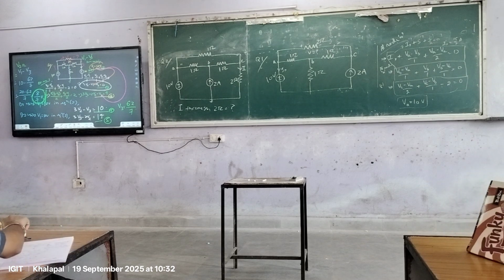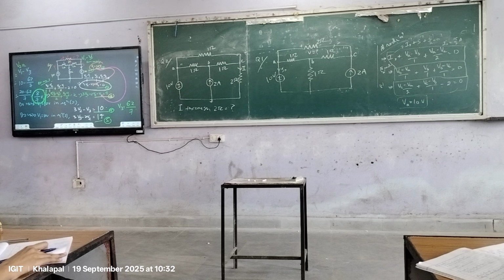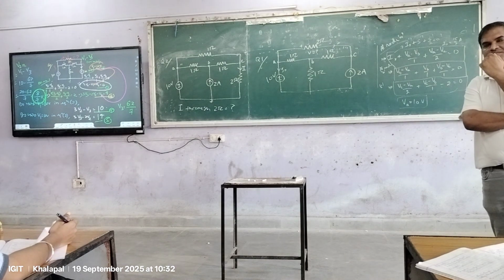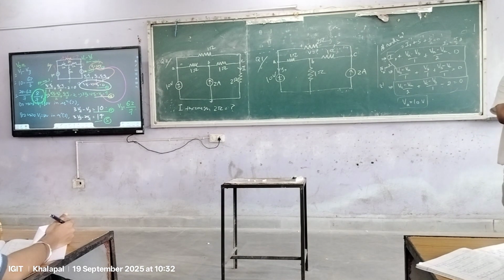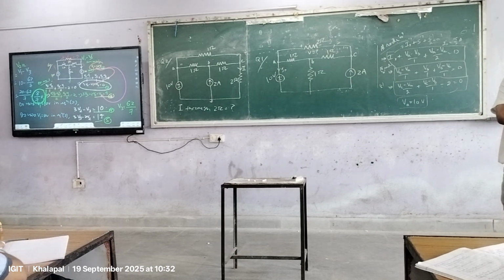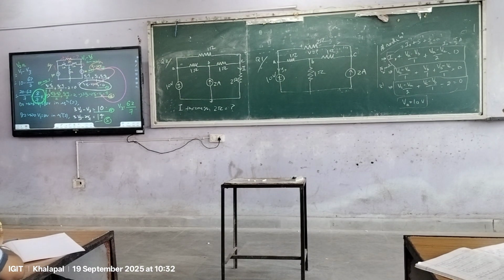Which did you find easier, mesh or nodal analysis? Yes, nodal is comparatively easier than mesh. But remember, if a circuit contains a larger number of current sources, it is advisable to use mesh analysis. If a circuit contains a larger number of voltage sources, then it is wise to use nodal analysis. Do remember this.